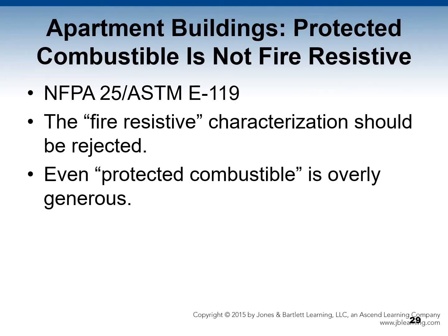Protected combustible, quote unquote, is not fire resistive, quote unquote. Floor and ceiling assemblies and interior walls can be rated according to ASTM standard E-119. The fire-resistive characterization should be rejected. Even protected combustible can be overly generous. They're just misleading terms. They suggest that things might be a little bit safer, but that's the way it needs to be regarded, not I'm fully protected now, just like the unsinkable Titanic.